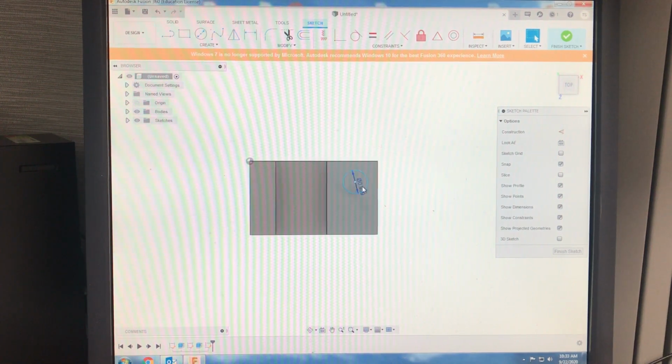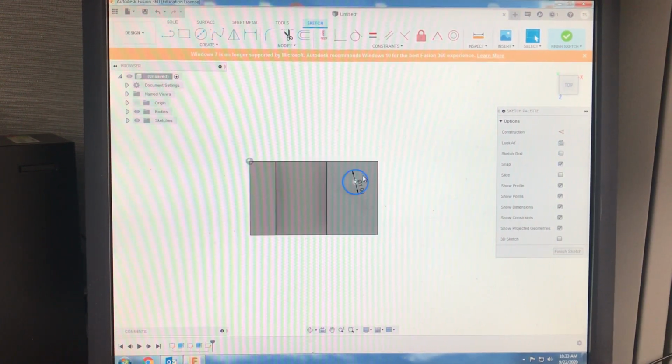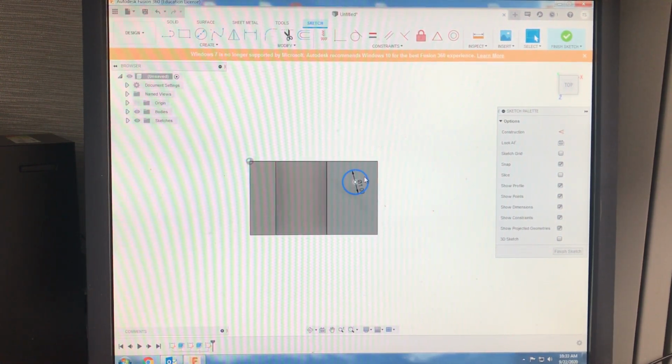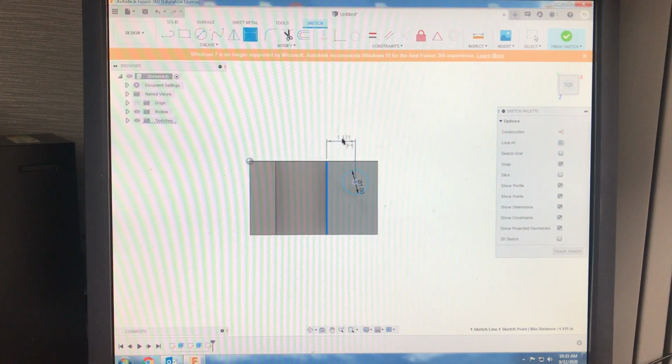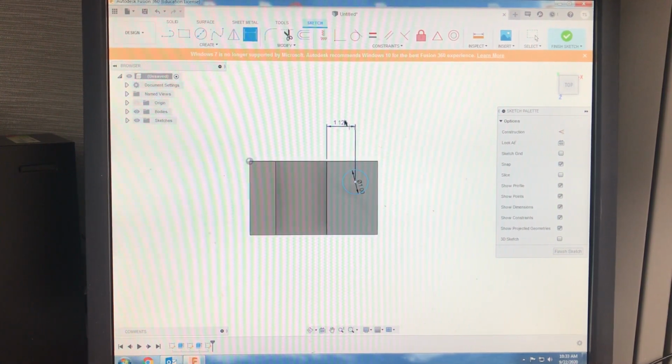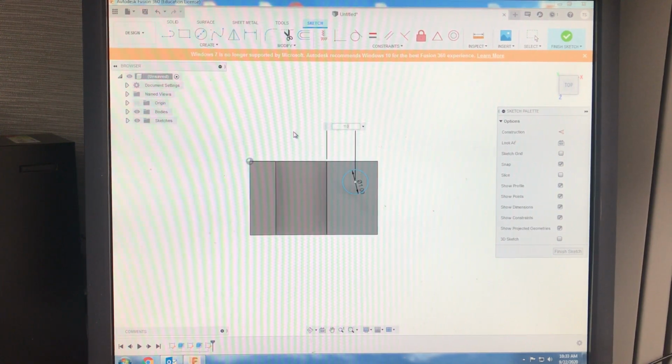That is not right. You can double click it if it's not right. I must be fat fingering it. Alright, so now we've got a circle right here. It's not really where we want it. Again, we go back to D. D is your favorite button. D, I'm holding it down, dimension it from here to my center, and go up. We know that is 1 inch.